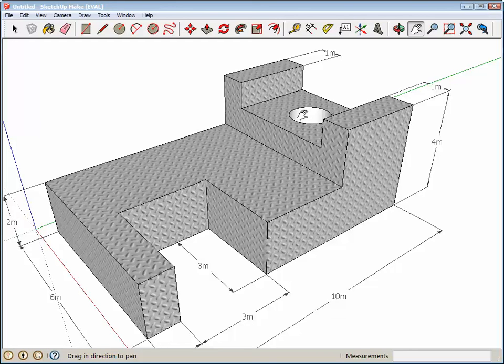We could show the dimensions of that circle, and if you wanted, the location of the center of that circle. If you want to go ahead and do that, you can, but all that I'm going to require on this one is that you add a label and just kind of point right there at the center, like that, and then make sure that held on very well. See if I can get it to go to the circle. There it is. That's what I was looking for. So you go here, enter some text. In this case, it would be 0.75 meters through hole, and this is how they spell through in drafting.